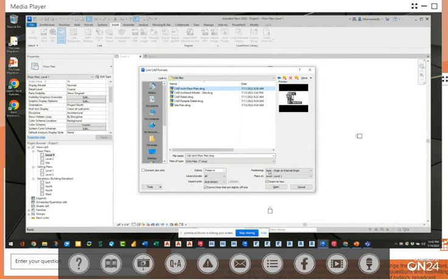into this project. Now, what's important about bringing anything into your Revit templates or your project when you're starting it out is to know what they call the positioning, the coordinate system, right? How is it built? Is it center to center, origin to origin? Is it shared coordinates or like a campus project, right? So you have your options here for positioning. Auto origin to origin, or origin to internal origin, is in AutoCAD what we call 0, 0, 0, right?